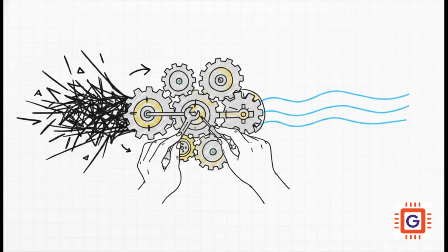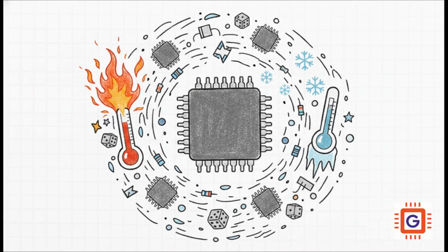The masters know exactly how to mitigate these disasters by diving deep under the hood. They tweak specific engine parameters, like adjusting the .options CONVSTEP, or carefully modifying relative tolerances. They gently guide that mathematical engine right past the bump without sacrificing the integrity of the data. And they have to do all this while accounting for process variations. Because silicon chips have to work flawlessly in some incredibly unforgiving environments.